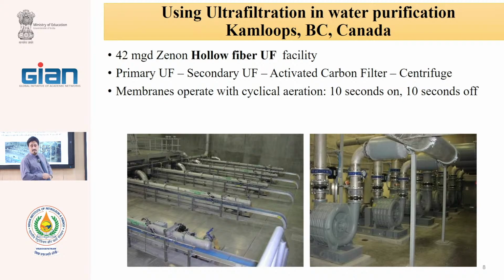Why use the activated carbon after UF? What is the role of the activated carbon filter? Adsorption. Adsorption of the organic pollutants. Some small organic pollutants cannot be removed by UF.